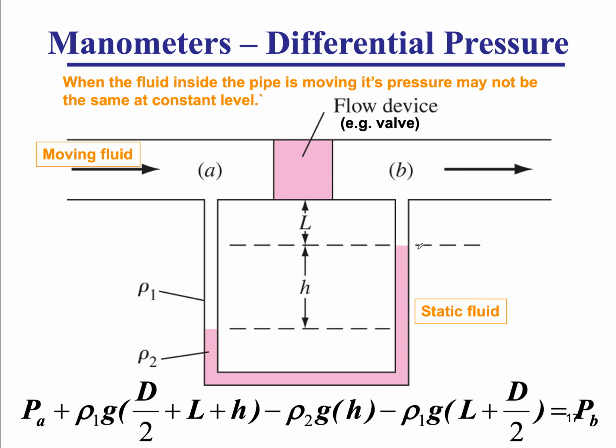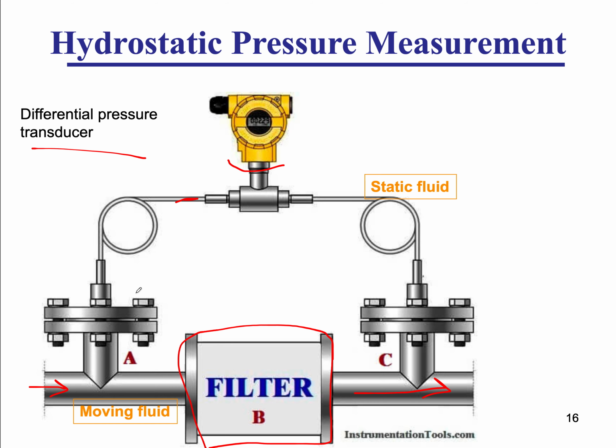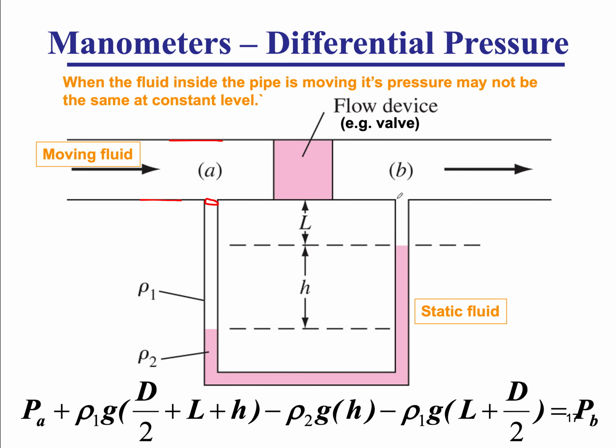And that's how we implement this. That same story we implement with a fluid-filled manometer. So I have a pipe right here, and I drilled two very tiny holes. Unlike this system where the transducers are connected through big flanges, I could just drill a very, very tiny hole here and here, just millimetric holes, and connect the two ends of the pipe to the U manometer.